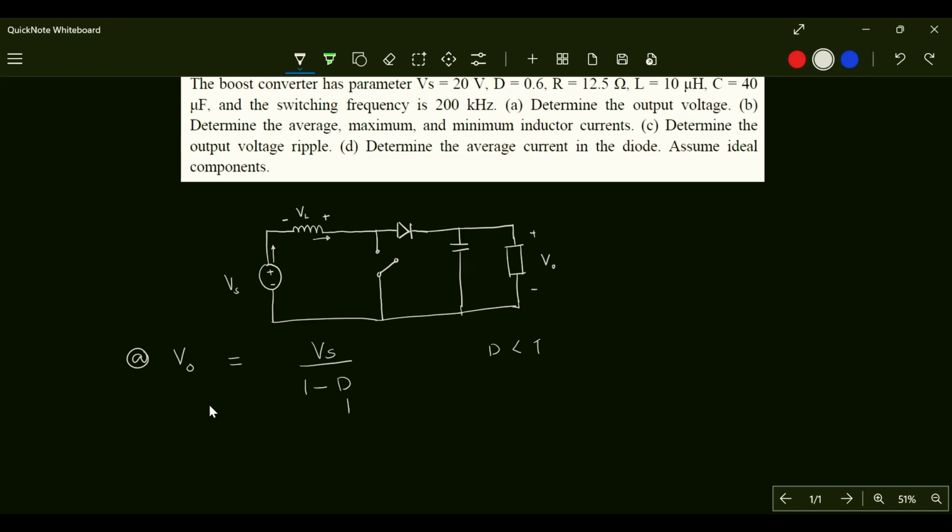And this output voltage also depends on the duty cycle, as you can see. So if the duty cycle goes up, meaning that the period between on and off is very small, we have a waveform like this, right? So this is off period, and then at this point this is T. And then you start again, and then it's off, and then 2T at this point. Just like that, and then this time is off, 3T. So this portion of the waveform is D by T when it's on, duty cycle by time period, and then this one here is 1 minus D by T.